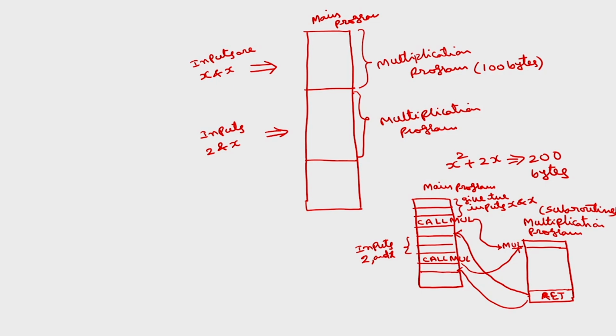But here the problem is, whenever the microprocessor is executing this call instruction, the instruction which is to be executed next is this. So, the instruction pointer will hold this address. Suppose the offset of this particular memory location is 6000 H, the instruction pointer holds this 6000 H. Then if I do not save the instruction pointer contents and I go to this subroutine, while returning, how does the microprocessor know that it has to return back to this 6000 H?